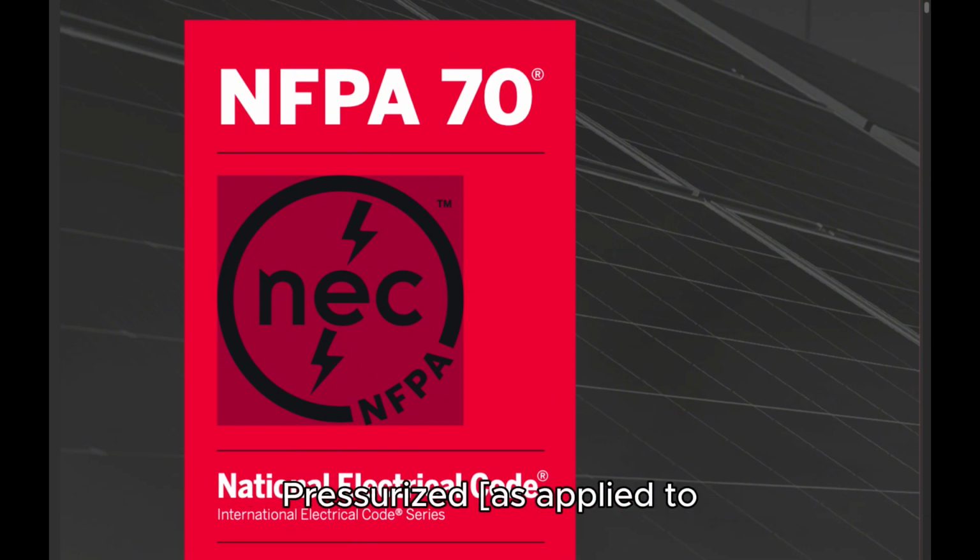CMP14 Purged and pressurized, as applied to hazardous classified locations. (1) Purging. Supplying an enclosure with a protective gas at a sufficient flow and positive pressure to reduce the concentration of any flammable gas or vapor initially present to an acceptable level. And (2) Pressurization. Supplying an enclosure with a protective gas with or without continuous flow at sufficient pressure to prevent the entrance of a flammable gas or vapor, a combustible dust, or an ignitable fiber. CMP14 Informational Note: For further information, see ANSI/NFPA 496-2013, Purged and Pressurized Enclosures for Electrical Equipment.